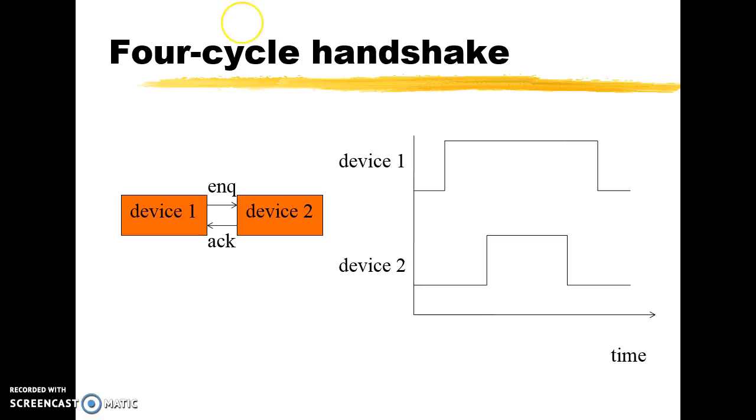Next, we're going to discuss the 4-cycle handshake. In this, the CPU serves as a bus master and initiates all transfers. If any device could request a transfer, then other devices must be starved of bus bandwidth. As bus master, the CPU reads and writes data and instructions from memory. It also initiates all reads or writes on input-output devices. The basic building block of most memory bus protocols is the 4-cycle handshake.